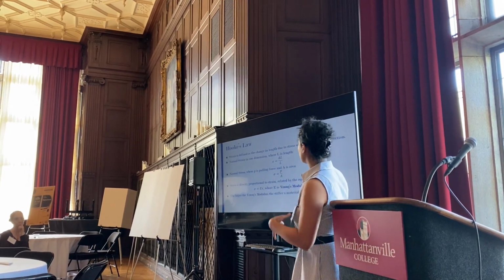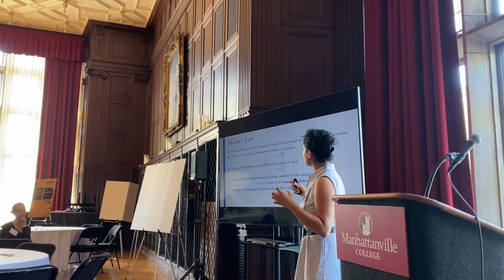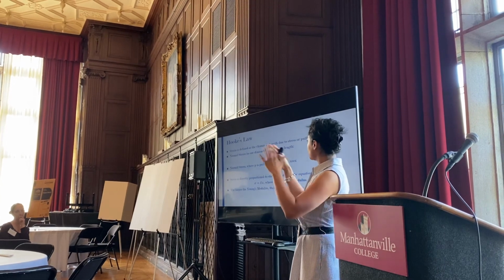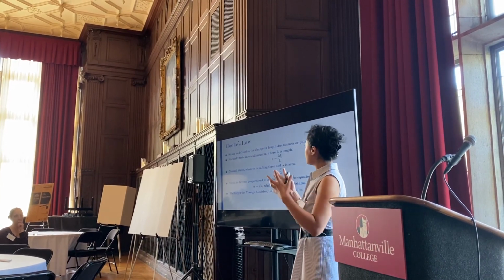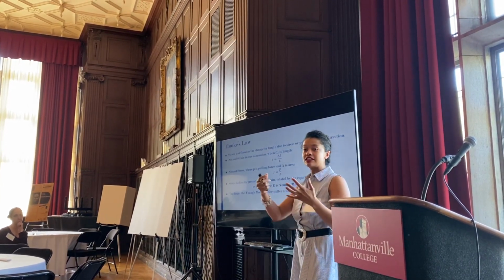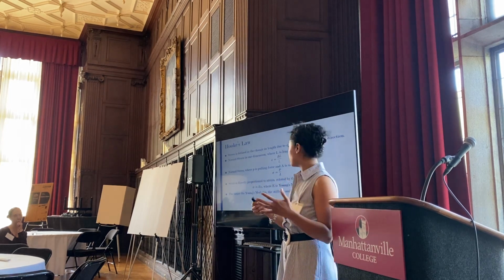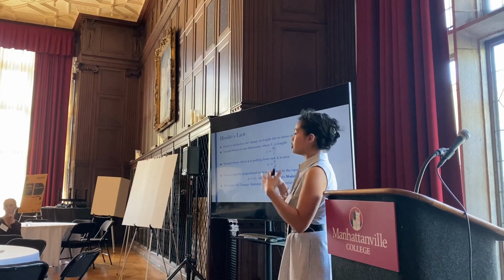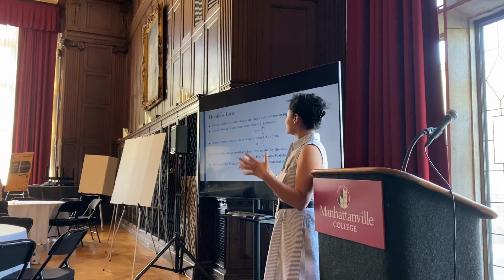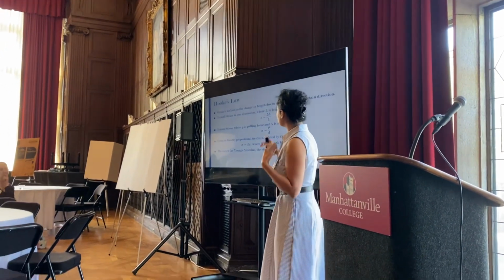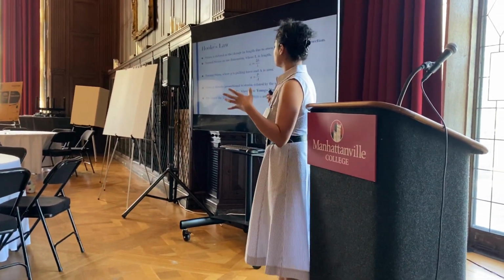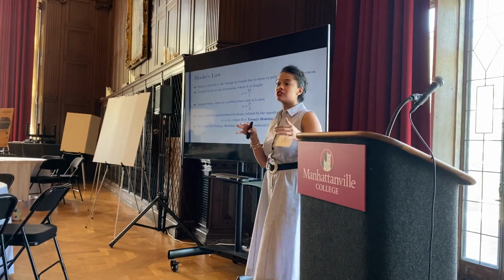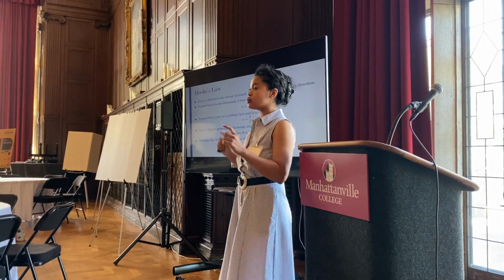Following that, we go to Hooke's law. In the first dimension, Hooke's law has to do with the change in length over the original length. That is strain. It is the change in length based on stress or pulling. Normal stress in the first dimension is the pulling force over the area of the thing you're working on. Stress can be directly correlated to the strain using Young's modulus. Young's modulus is one of the values we changed in each trial of this experiment.